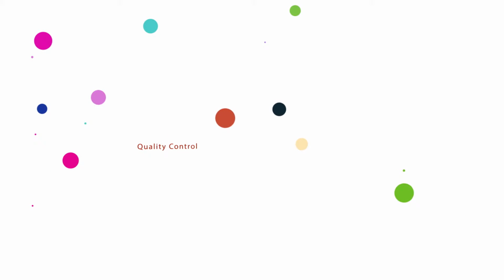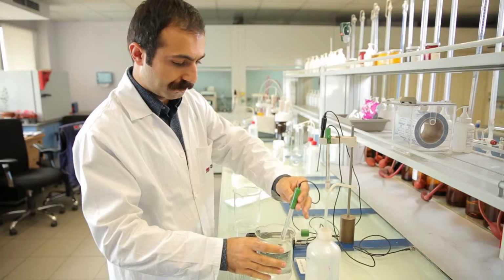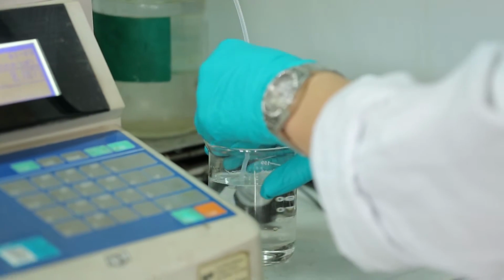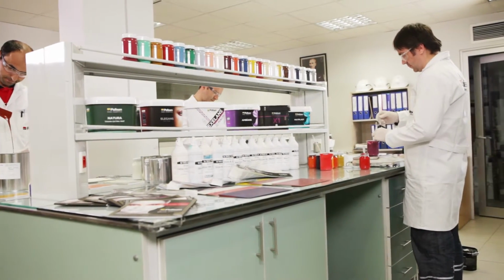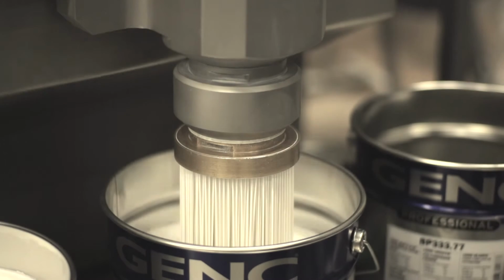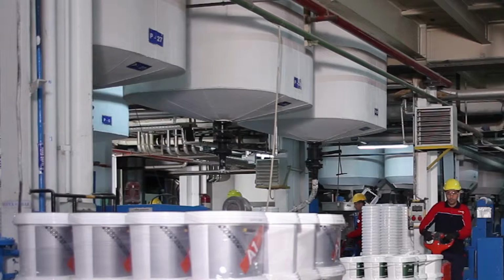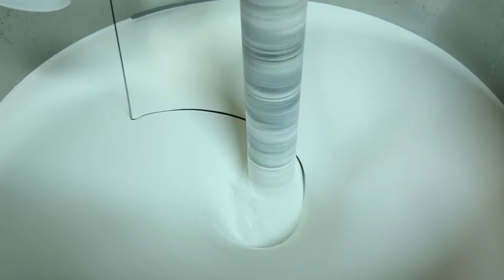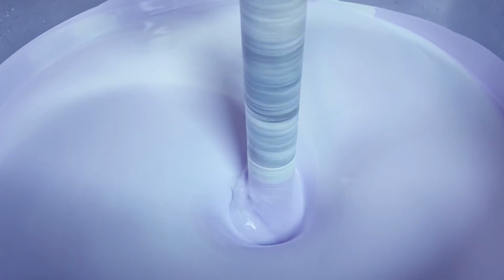Quality control. By sampling from the final product, basic controls such as pH, viscosity, density, luster, etc., and, as appropriate, additional tests such as solid substance, colour, concealing, etc. are performed. Transfer to stock or colour tank, colouring. If the product to be produced will remain white or filled as base, it is transferred to the filling process. If it will be coloured, it is transferred to the colour vessel. Colour paste is added to products transferred to the colour vessel to provide colour.